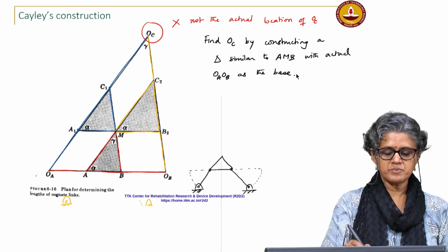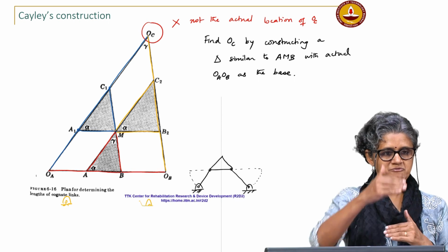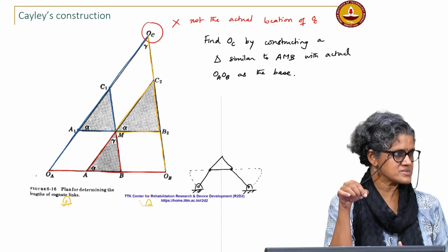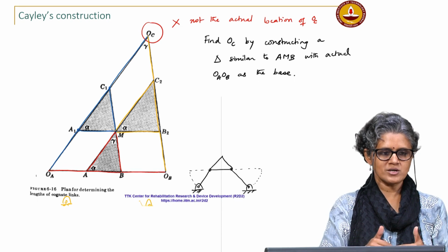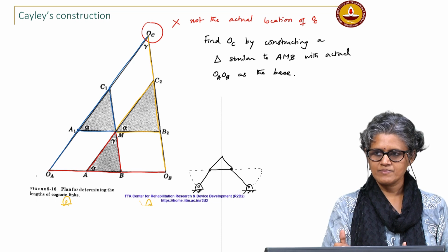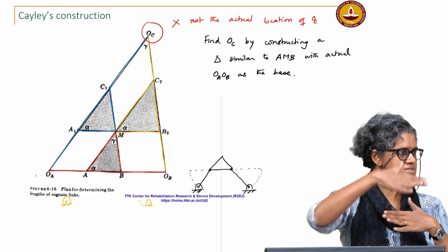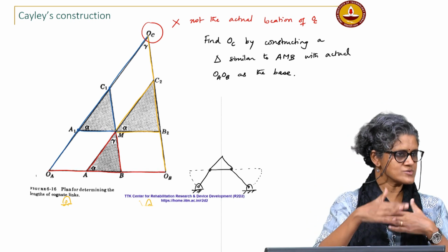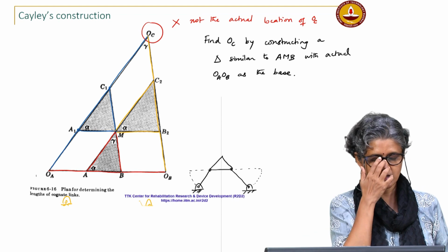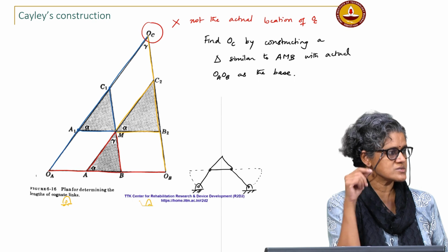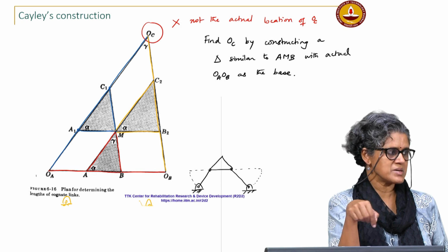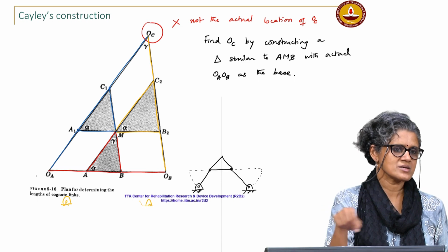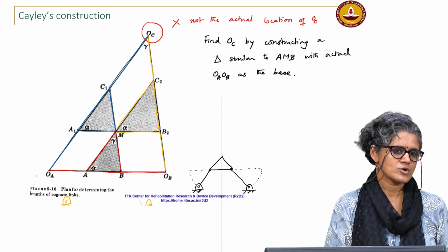So, suppose you have a coupler point that is not away from the coupler base, say it is on the coupler base, right. Essentially this whole thing collapses now. M is on AB, okay. So, it is like this whole triangle just flattens out, right. You can still use the similarity, the ratio in which M divides AB, you can use that to construct the coordinates for that. I will show you an example tomorrow.